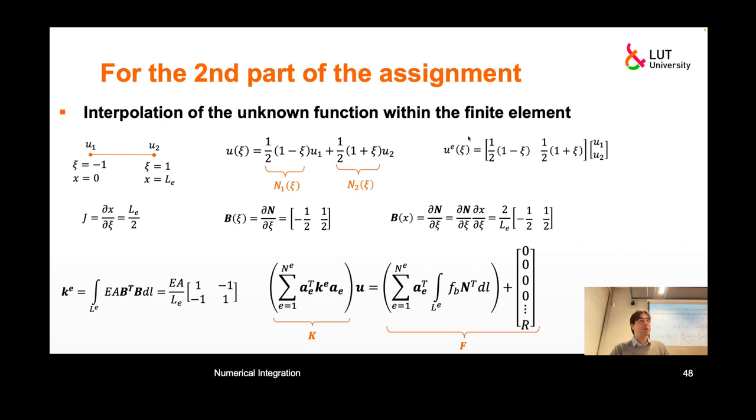And this matrix expression for the interpolation of displacements using nodal values will look like that. And we can calculate those derivatives of shape functions, this matrix of shape functions, with respect to xi, the only local variable that we have. It just gives us minus 1/2 and 1/2, a simple matrix. But this is in local coordinates. Again, I mentioned I did not show that in great detail.